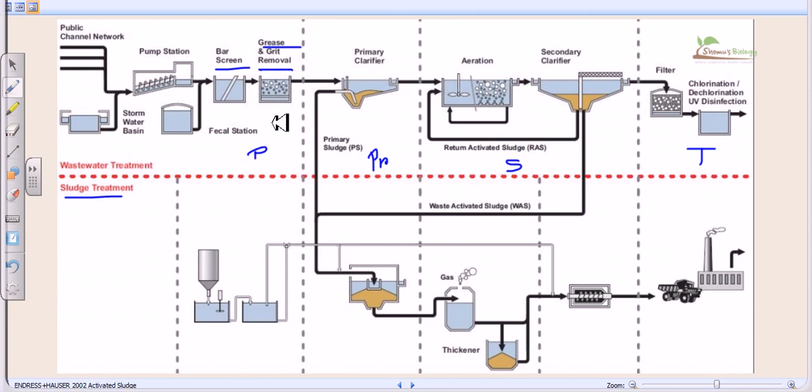We can see all the grease which we have collected, and which passes through the bar screens, can be coagulated in this step, and we can have grease balls forming which will float. We take those grease balls and scrape them off with the help of the scum removal, and we set them aside. It will remove all those grease materials, and right after that we end up with water that has small particles of other nutrient sources, but not the bigger particles, because all the bigger particles are removed in the bar screens and the grit removal system of the preliminary treatment.